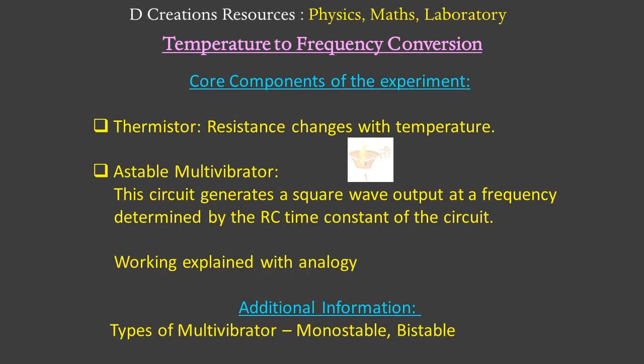That tells you that in the case of a monostable multivibrator, there is mono, that means one stable state and one unstable state. So it requires an external trigger to switch to the unstable state, and it will return to the stable state after a set time. So it's often used as a timer or pulse stretcher. Then bistable multivibrator.